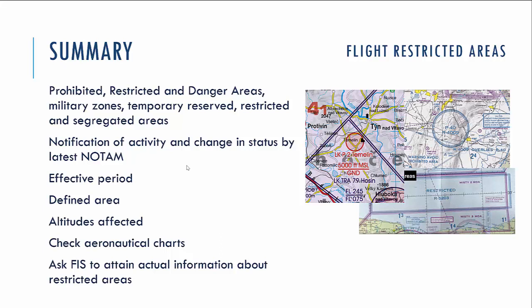In case those restricted areas are temporarily active, better to check the latest NOTAM, notice to airmen, to check the activity and change of the status. Again, if you are unsure about the activity of those zones, better to ask Flight Information Service to obtain actual information about the restricted areas on your route.